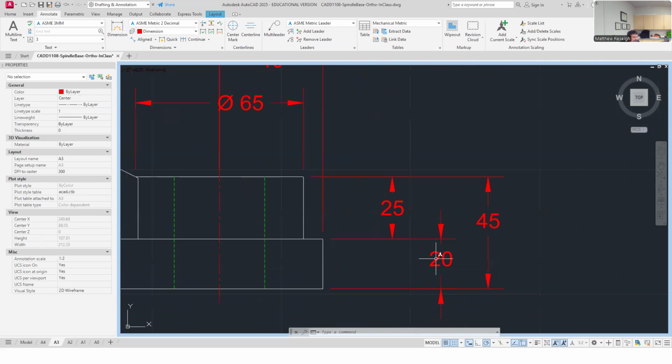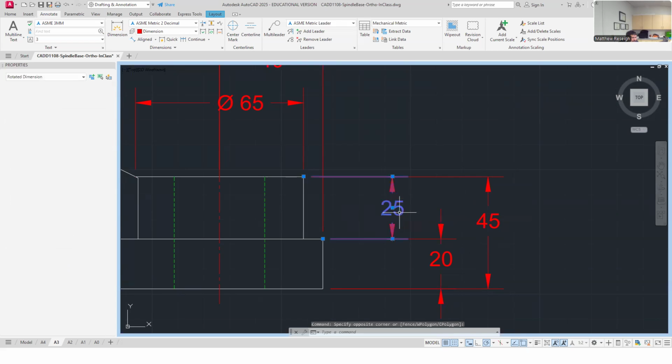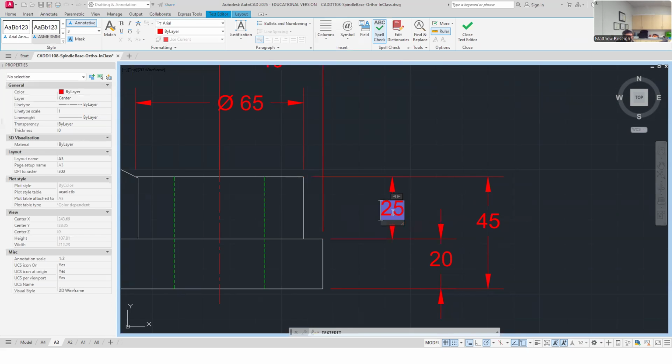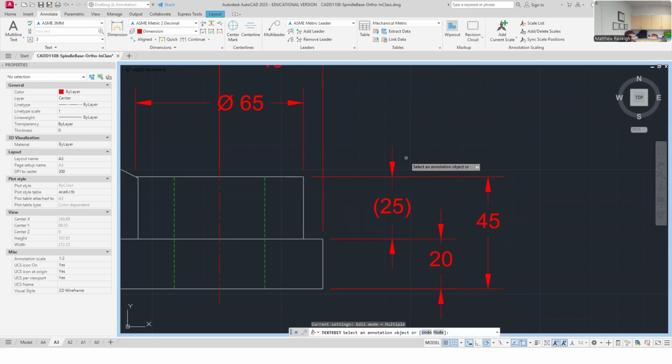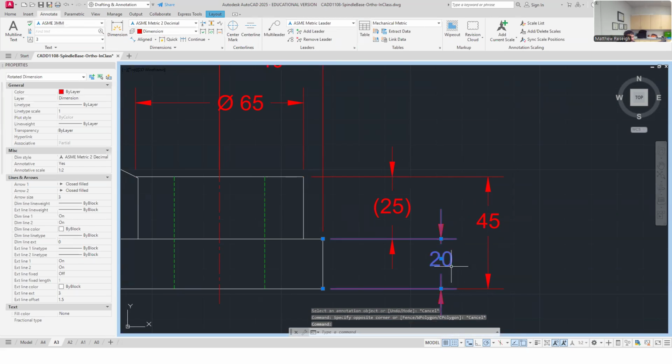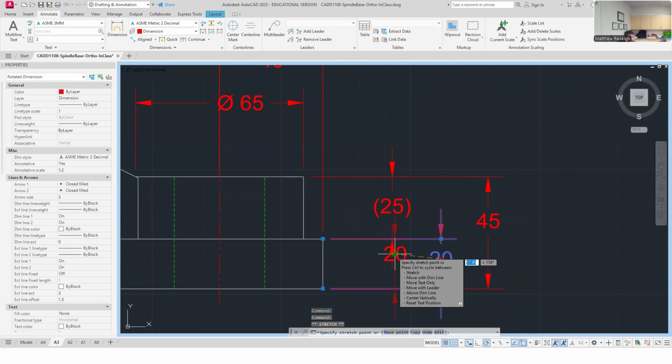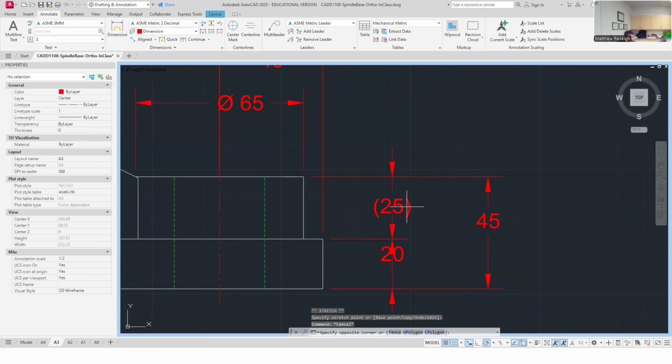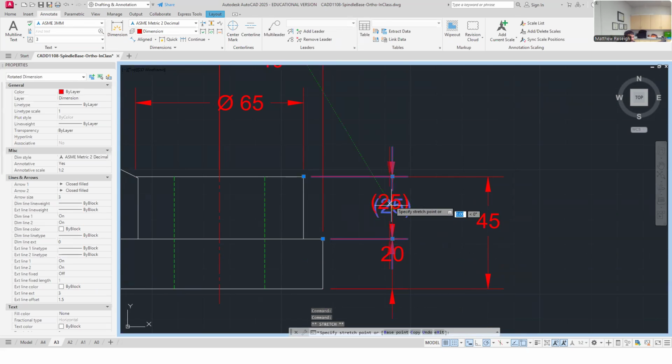And what would keep it from being chain dimensioning is if I said that this one is going to be the controlled surface. It can't be any more than 45. And so in that situation, if 45 was the most critical dimension, then this one would become a reference dimension like this. It'd be a nice to know. And I can even stack these up. So what I mean by chaining them, it's okay if these are kind of 2 intermediate dimensions. And it might be okay to do a lineup like this.